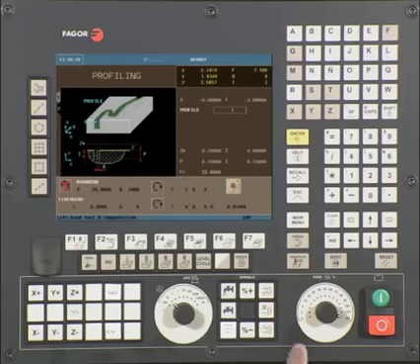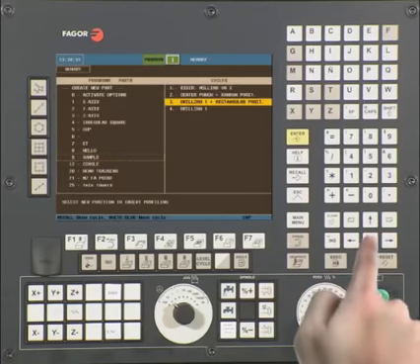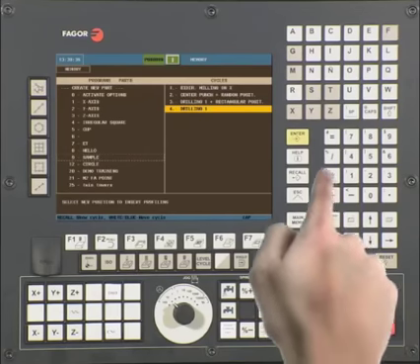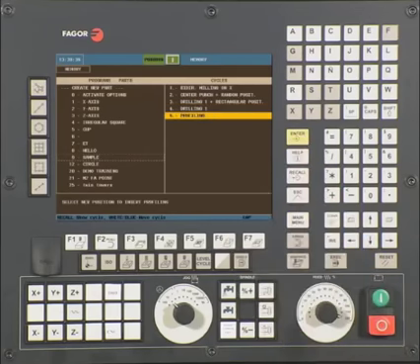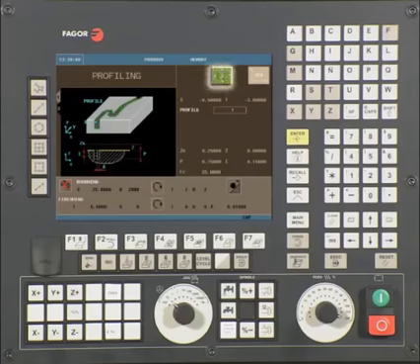Press the P program key. At this point, we should still be under the program we have created. If not, navigate back to the program. Once there, press Enter to insert the profile cycle into the program. To execute the cycle, press Escape twice. You now see that there is a Cycle Start icon at the top of the screen.